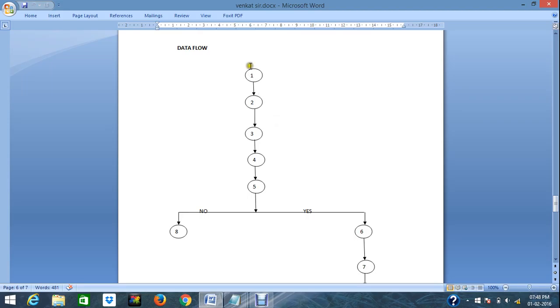As the driver applies the brake, next the brake fluid pressure will increase. Then there is a speed sensing sensor. It will sense the speed of each wheel. Then the lock will be detected.